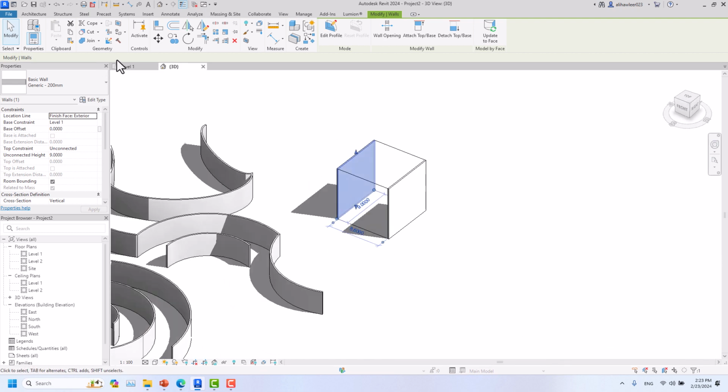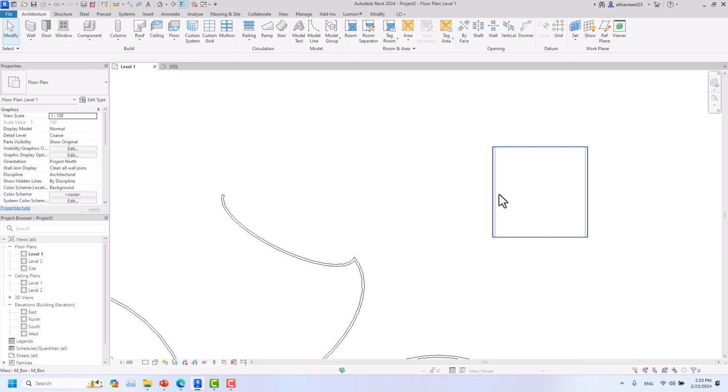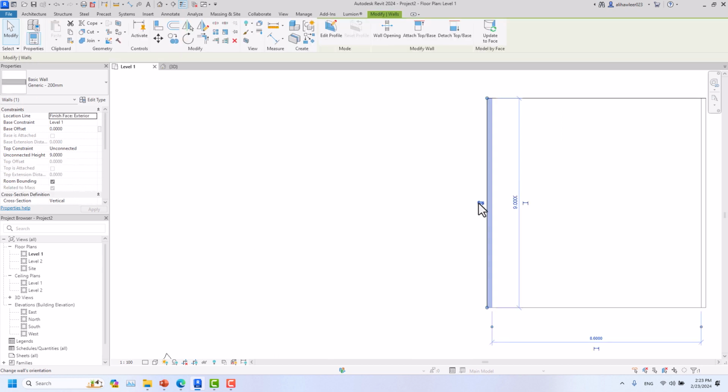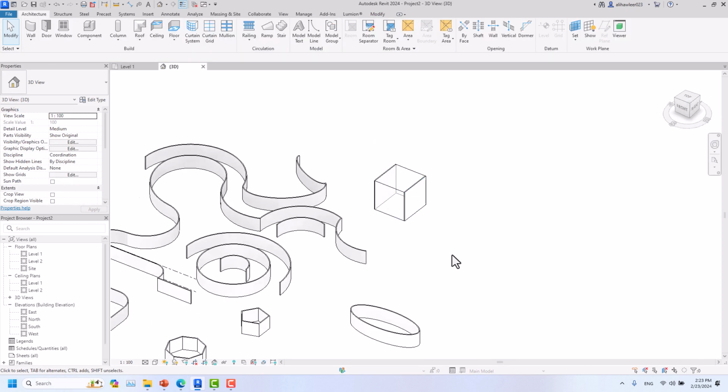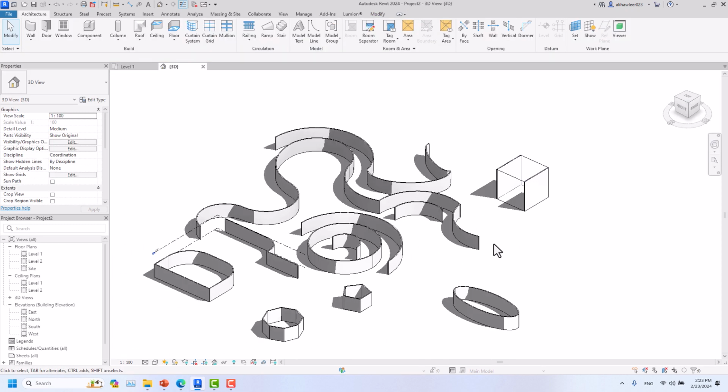Okay, like this. Let me go to here, and you can select the wall and try to insert it inside or outside. Okay, like by these arrows. Change the wall's orientation. It goes out or inside. See, if I click on this, I can make one of them go out. This one is inside. So this was it for today, and see you in the next video.